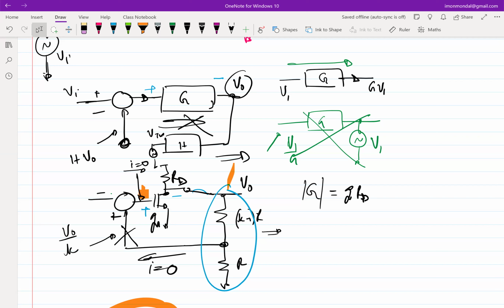Agree, but how are you going to push? Think in terms of where you are going to add the VDD. Let's say I want to establish a current I naught into that transistor. Now I'm talking about bias currents, right? So how are you going to ensure that the bias is provided while keeping the transistor in saturation? There are many ways. Can you think of one? To keep the transistor in saturation.